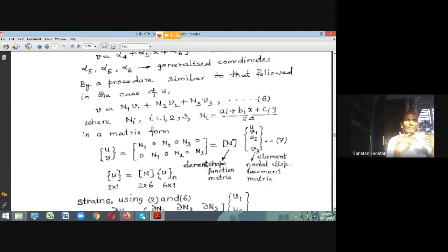And then you have hybrid formulation, where both displacement and stress assumed formulation can be there. Assumed displacement based, assumed stress based. These are the two different formulations. But somebody can have an assumption of displacement surface and also stress surface together. That is hybrid formulation.